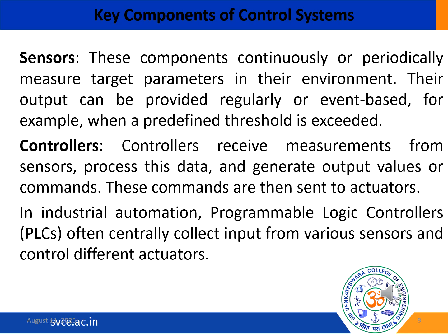The output can be provided regularly, or it can be generated event based, for example, when a predefined threshold is exceeded. And regarding controllers, controllers receive measurements from sensors, process this data, and generate output values or commands. These commands are sent to the actuators. In industrial automation, programmable logic controllers often centrally collect input from various sensors and control different actuators.